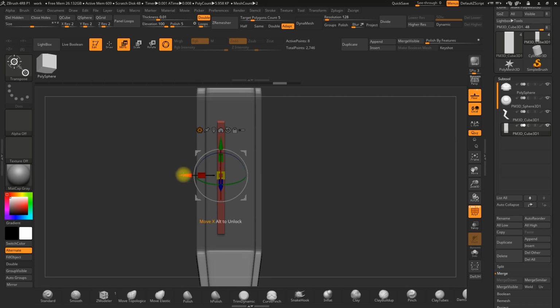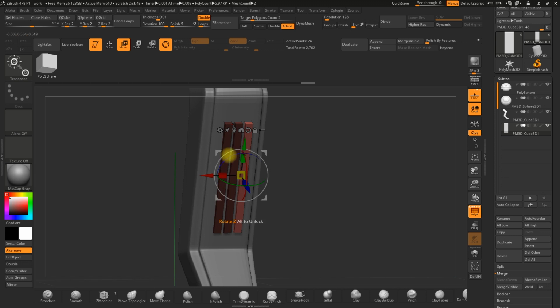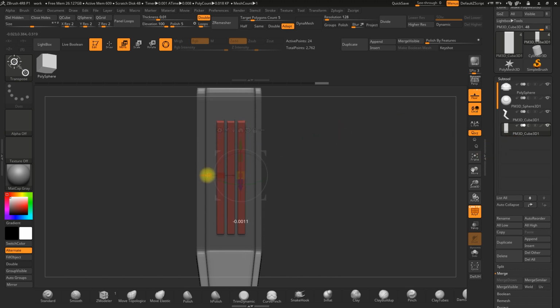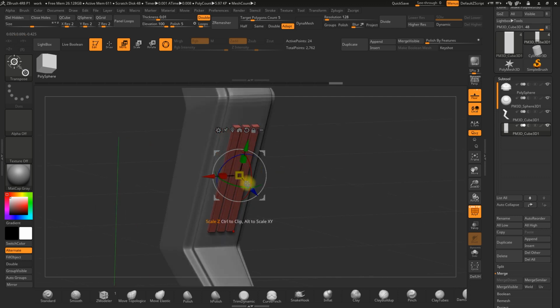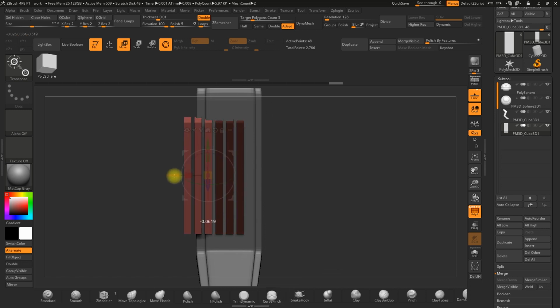Now, pressing Ctrl, if we move the object, a copy is made of the object that also joins the inactive object. So here we have these 3 elements. And as you can see, one doesn't have a mask and the others are inside a mask. So exit the mask, and we have these three elements joined together. This is also another way of modeling with this gizmo that makes it easier to make copies of the model pressing Ctrl.